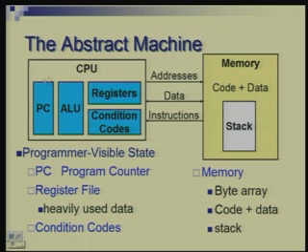The other block, or the heart of the whole system, is a CPU, where the key components, as I showed earlier, are a program counter, an ALU, registers, condition codes. Whereas the ALU is the one which basically performs all arithmetic and logical operations, the operands are contained in registers. So, they may have to be initially brought from the memory, and after having operated upon them, they are sent back to the memory. PC is the one which keeps track of the current instruction.